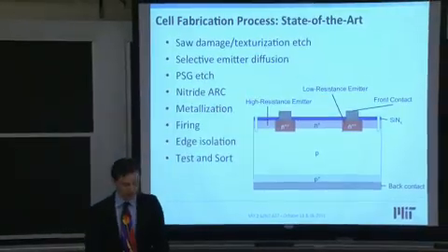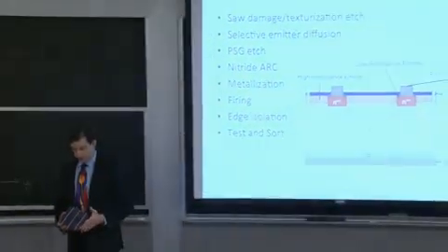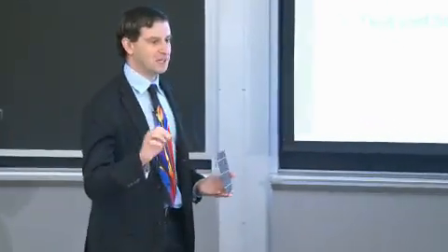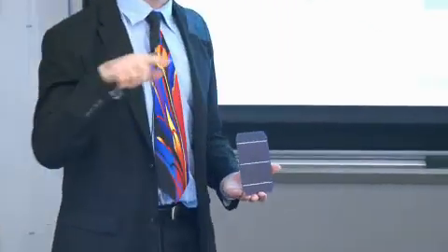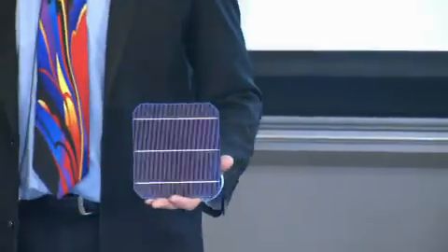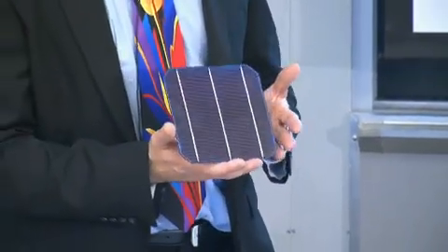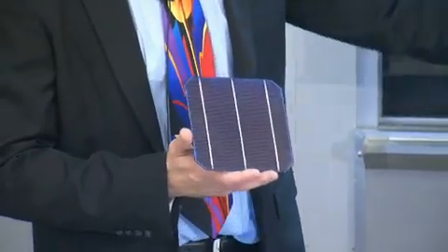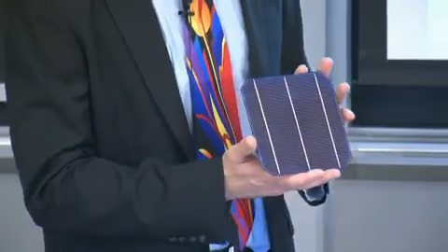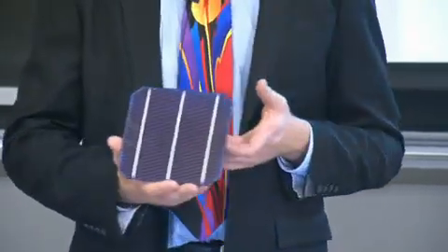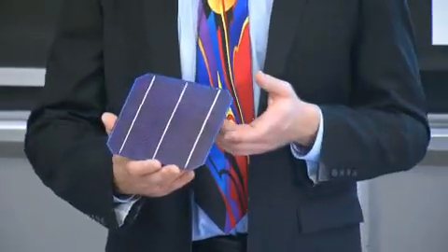And just from simple electrical engineering, and maybe as an extreme example, if you're stringing Christmas lights together, you know that if you have one bad apple, it can drag down the performance of the entire string, right, if you're connecting these in series. And so it makes sense to test each of the cells individually and make sure that you sort them together with their like cousins, right? So if you have high-performance cells, you bin them all together, and you make modules out of the high-performance cells. These will be high-performance modules. The bad apples you put together with the bad apples, and so forth. And that way, you can extract the maximum value out of the product you've created.